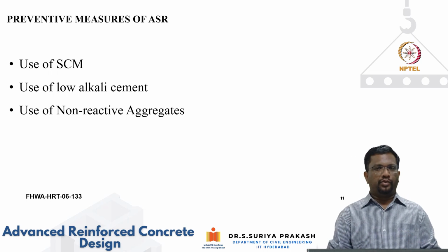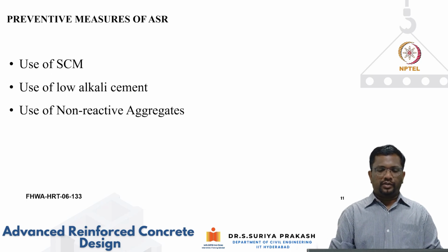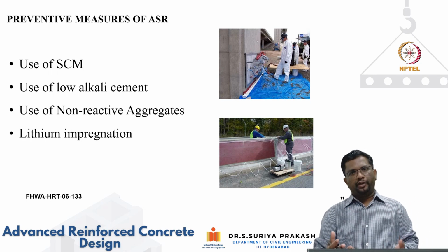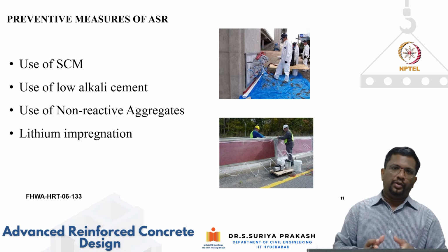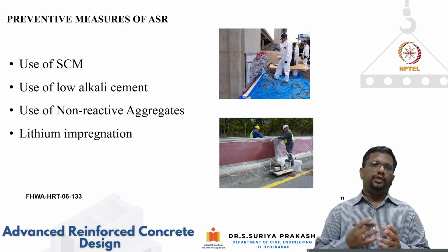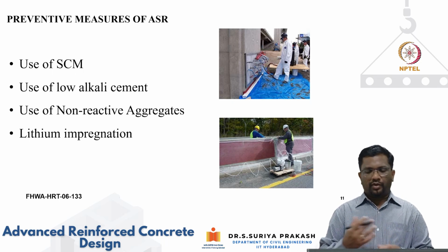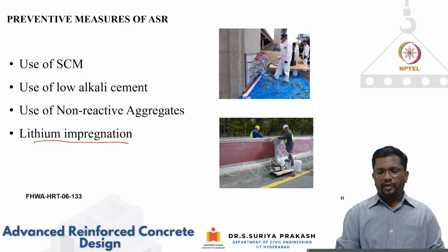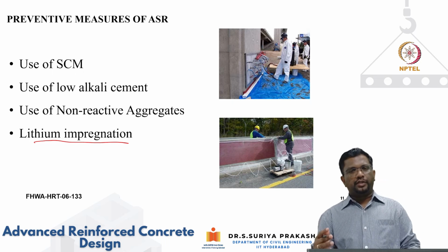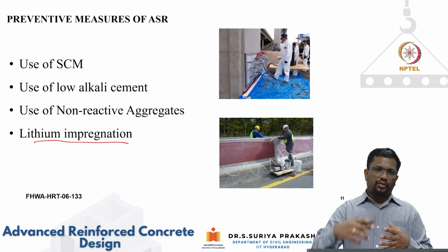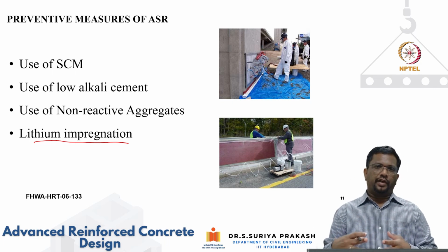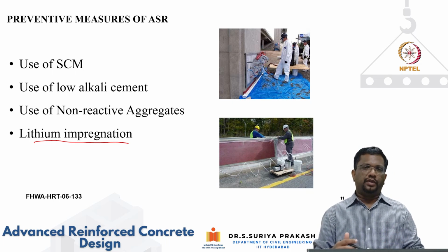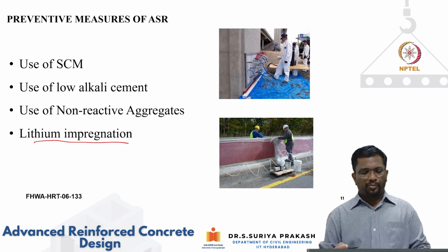So aggregates also have to be tested so that they do not have a reactive silica component. Now, let's say that you have already built the structure and you want to limit the cracking induced by these alkali-silica reactions. One intervention is lithium impregnation, which goes and coats within the aggregate, and it will not prevent the gel from forming.